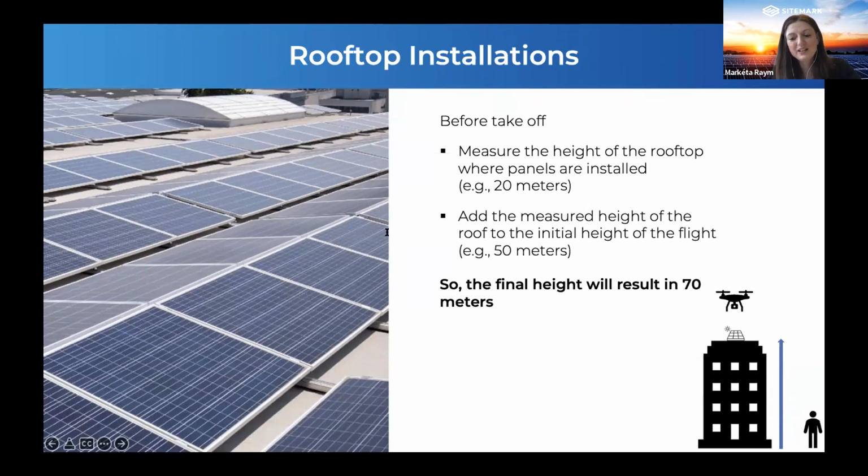It's actually better to stay a little bit longer and cover, let's say, a minimum of 20 images, having 4 flight lines above the building, and ideally a few flight lines also outside. That will guarantee sufficient overlap for the images and good data when they are uploaded, because sometimes the site seems small, pilots tend to take just a few images and leave the site, and we really know that. So it's really better to have a 5 minute longer flight with great images.